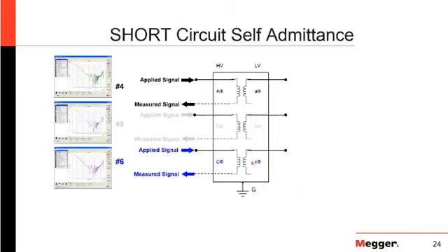And then what I would do is I would come over here and short the low voltage terminals and then apply the signal and measure through here. And then I can move my leads and go through B phase with these shorted and then go back and unshort while I'm connected to B phase. And then I would move to C phase, do that test, and then short again, just to save a little bit of time.